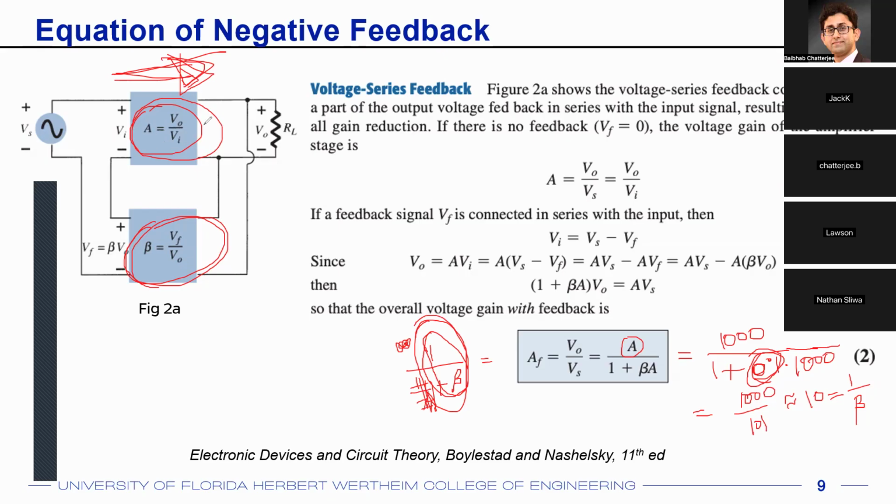That's just one example, the manufacturing variation, that's called process. Now there could be scenarios where there are voltage fluctuations in the system. There could be temperature fluctuations in the system. And if there are these process, voltage and temperature, or PVT, fluctuations in the system, the gain A keeps on varying significantly. If you do the measurement outside in the heat, you'll see a very different result for your gain A.